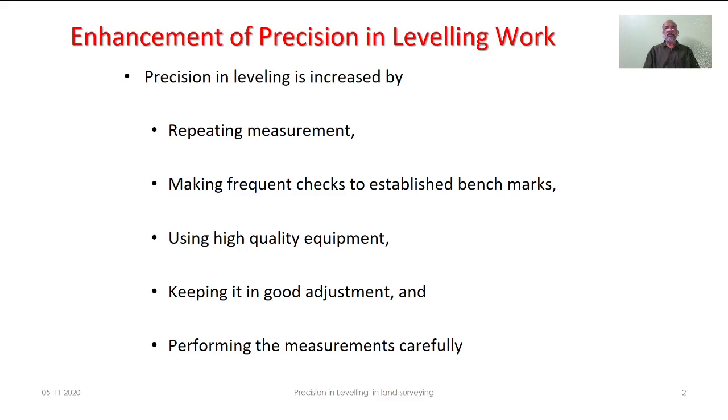To start with, already you know what is precision and accuracy as far as surveying terminology is concerned. So whenever we wish to have any surveying measurement, we want it to be precise yet accurate. By precision, we mean the measurements are close to each other, whereas accuracy wise, we wish to see that all those measurements are close to their most probable value.